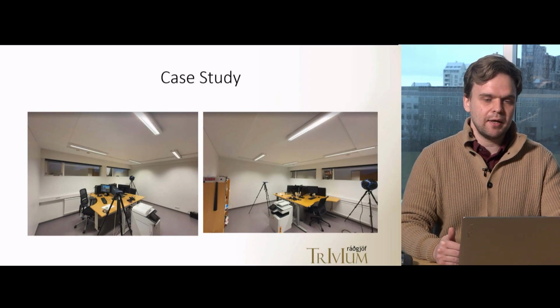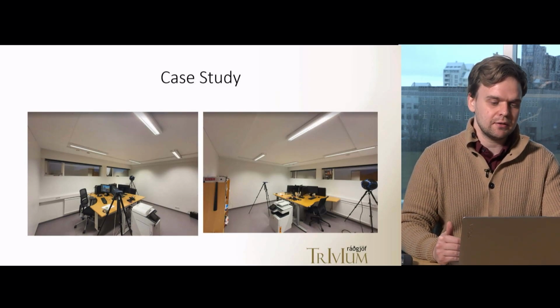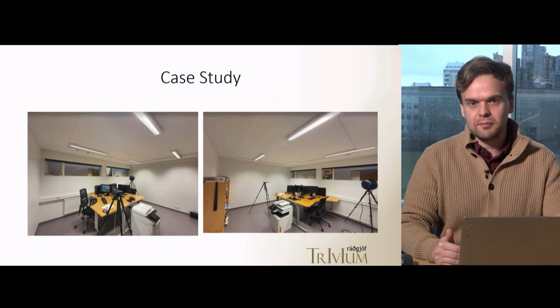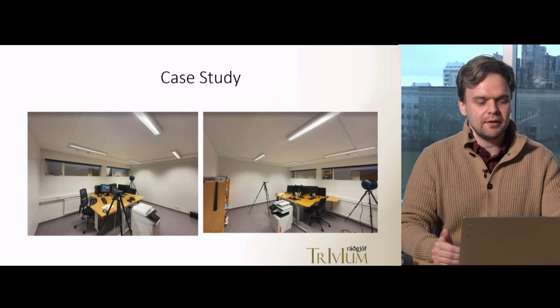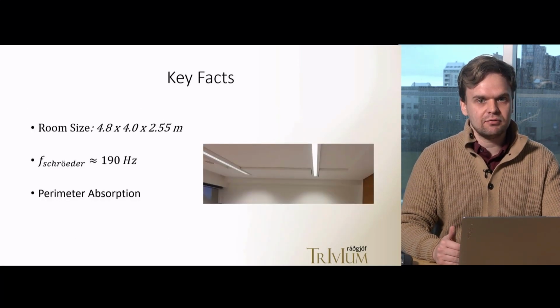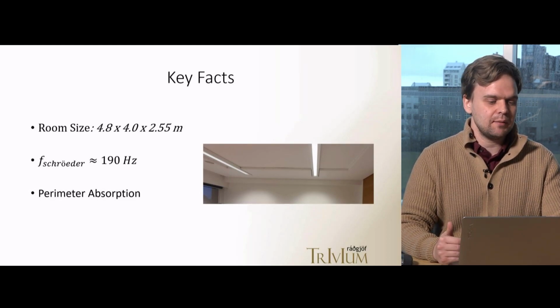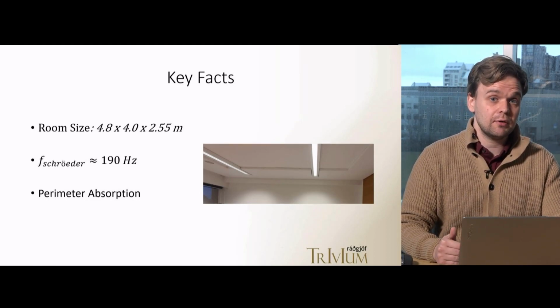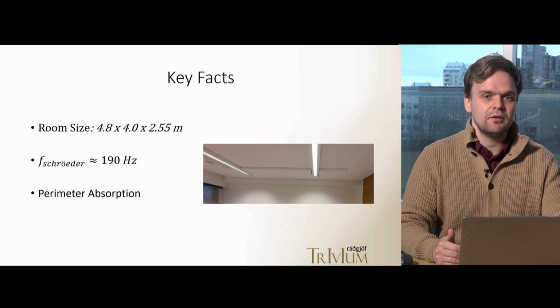So this being my office has a few advantages. Firstly, I can obviously do acoustic measurements whenever I want, at least when my neighbors are not at their own office next to me. And this being a small room is very relevant for Treble's strengths. You can see the key facts about the room here, the room sizes in all the major dimensions. The room has a Schroeder frequency of around 190 Hz,